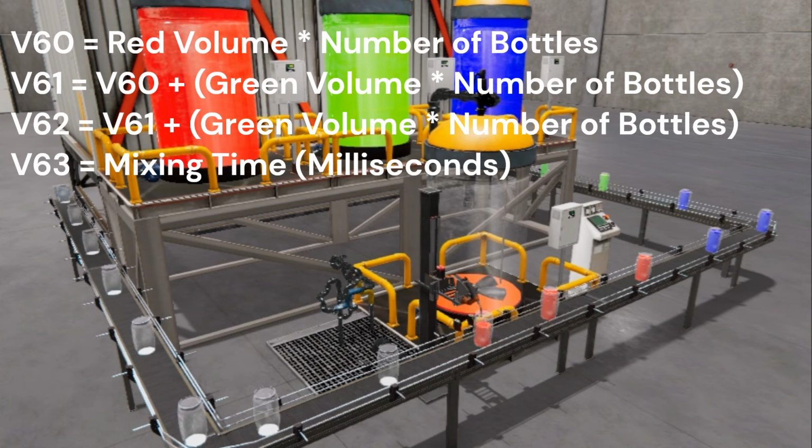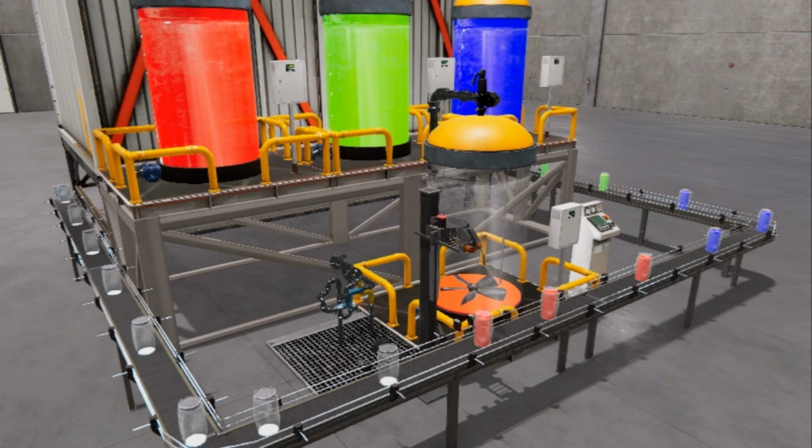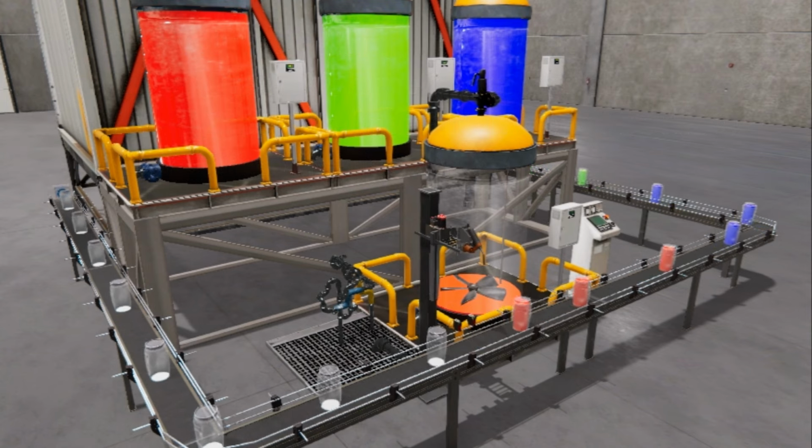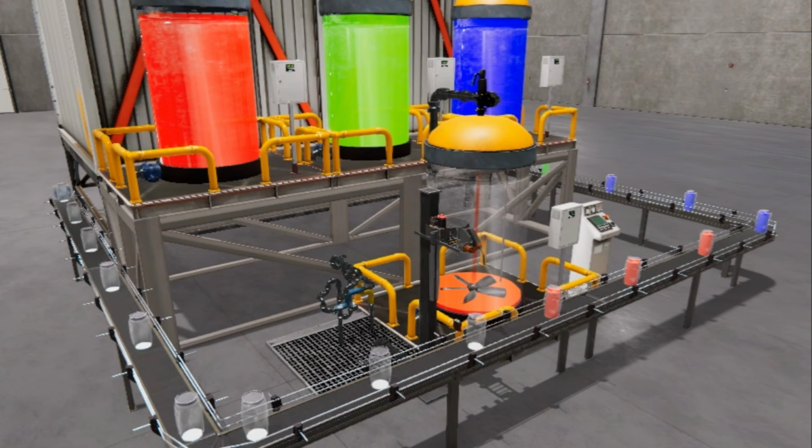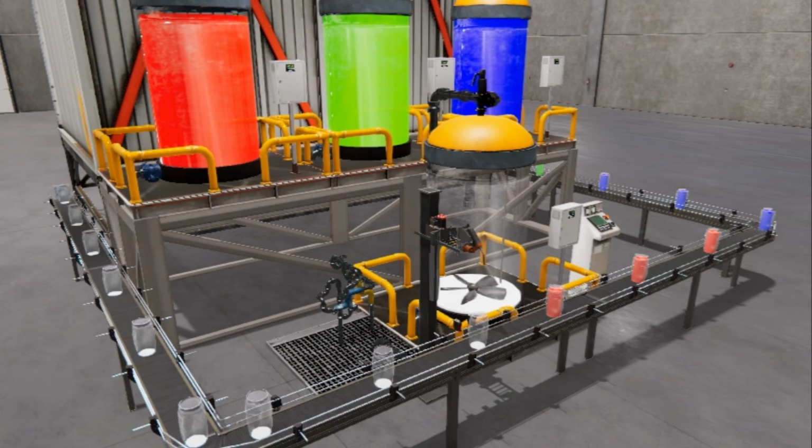Once all the colors are in the mixing tank, the mixer will turn on for the time in the recipe. Filling of the bottles can now take place. The filler will move down to the filling position when filling the bottles. The volume of the mixing tank minus the value of 100, full bottle, will be the target for the volume when the bottle is filled with ink.